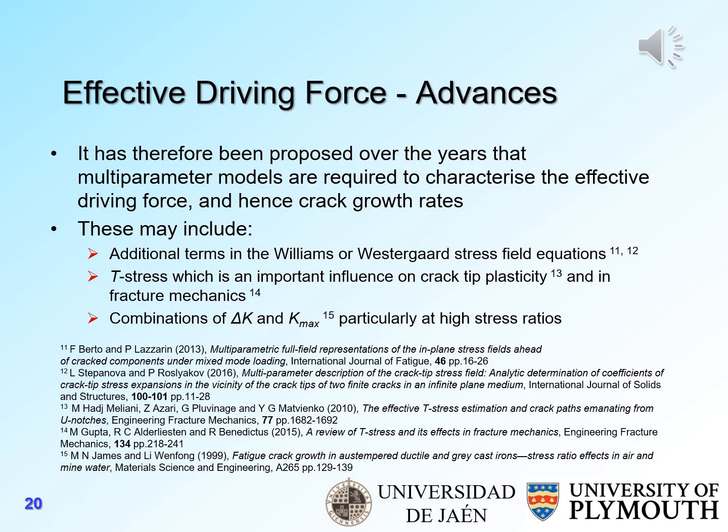So as I already mentioned, over the years these uncertainties have led to the proposal that multi-parameter models are maybe required to characterize the effective driving force on cracks and hence the growth rates. And these multi-parameter models include possibly additional terms in the Williams or Westergaard stress field equations, and I give you some references.